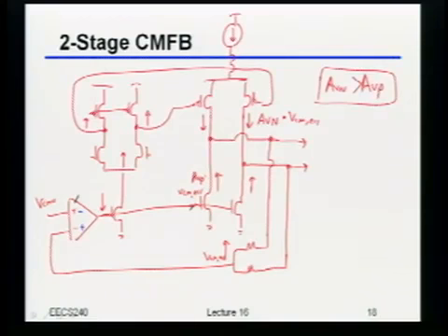Why in general do you add current sources onto things? Differential mode? Okay, well, differential mode versus what? Common mode. Right, okay, so what's the common mode gain of something like this? Yeah, it's supposed to be 0, right? It's supposed to be small, because this current source is supposed to just throw away all the common mode, right?